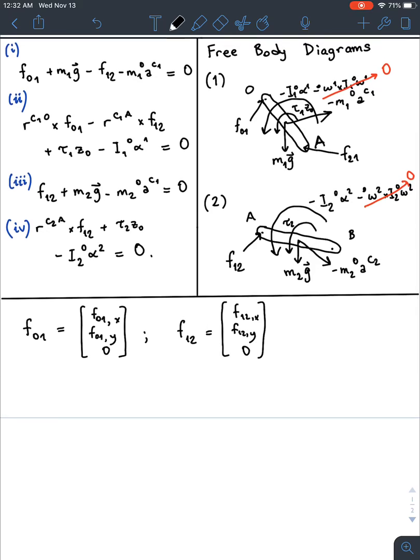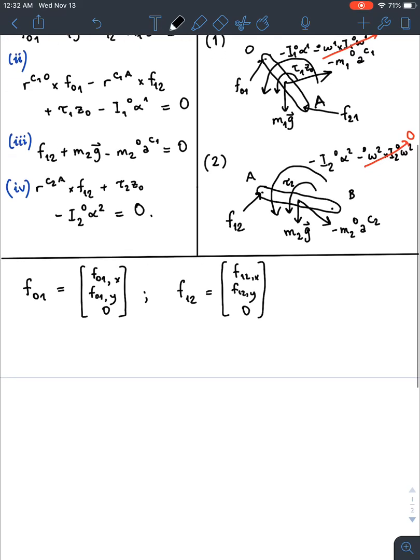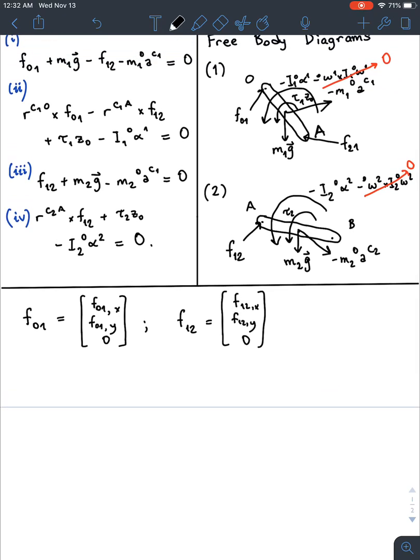So next, the other unknowns are of course theta 1 double dot and theta 2 double dot. Since those are the unknowns, I'm going to work on expressing the acceleration of C1 in terms of A1, theta 1 double dot and theta 2 double dot, and similarly the acceleration of the point C2 in terms of theta 1 double dot and theta 2 double dot. Okay, I had made a mistake here. I corrected that. It read acceleration of C1 in 0. It should have read acceleration of C2 in 0. Of course, this is for the second rigid body, so it must be the acceleration of the center of mass of that rigid body.